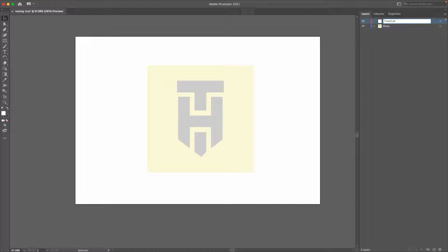So once you name this other layer, come down here to the first layer and lock it so that you don't get into contact with it or interrupt it. So it's locked, that's why I can't even select it right now. So the pen tool is next to this direct selection tool, and it also has its name clearly written in the drop down.